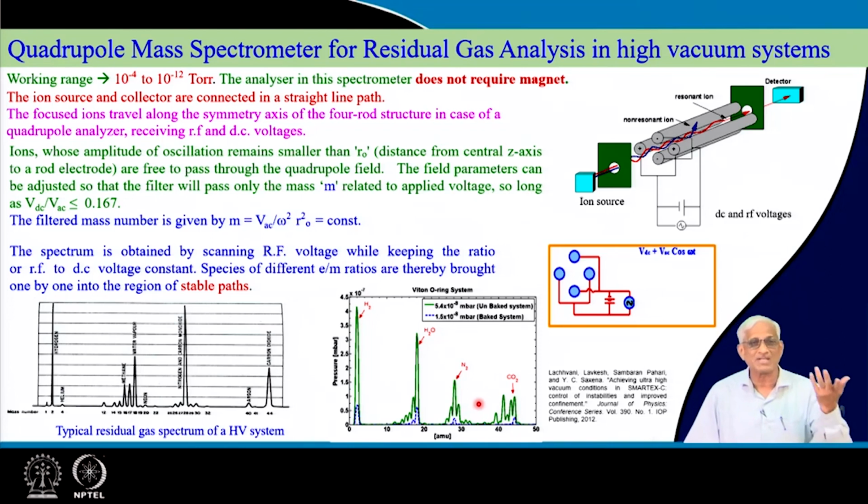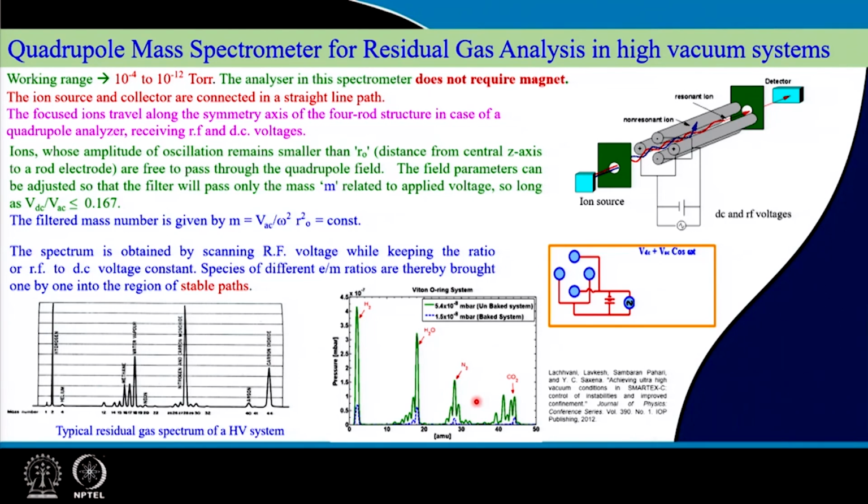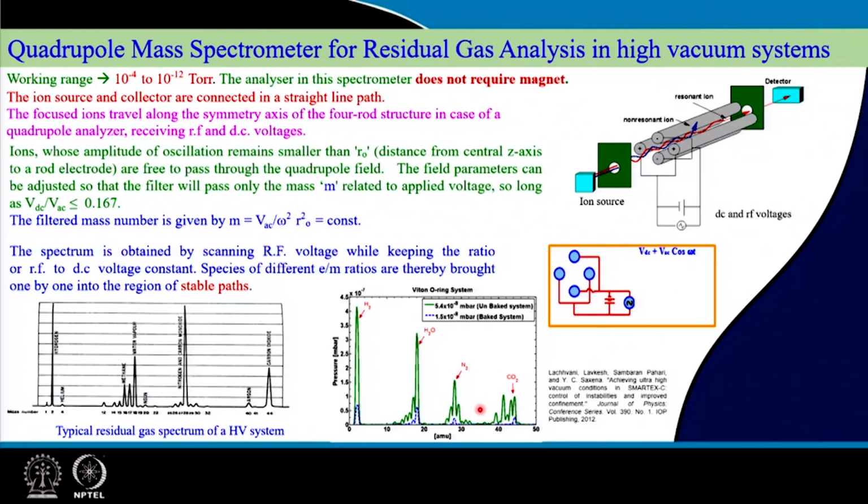From that you can understand very nicely the problems associated with the vacuum system. This is one way of troubleshooting chemically. Another way is to link it to a particular mass. That means, for the same spectrum, you do not scan it; you link it to helium, and then it is stable always only with that, and you can use it as a leak detector.